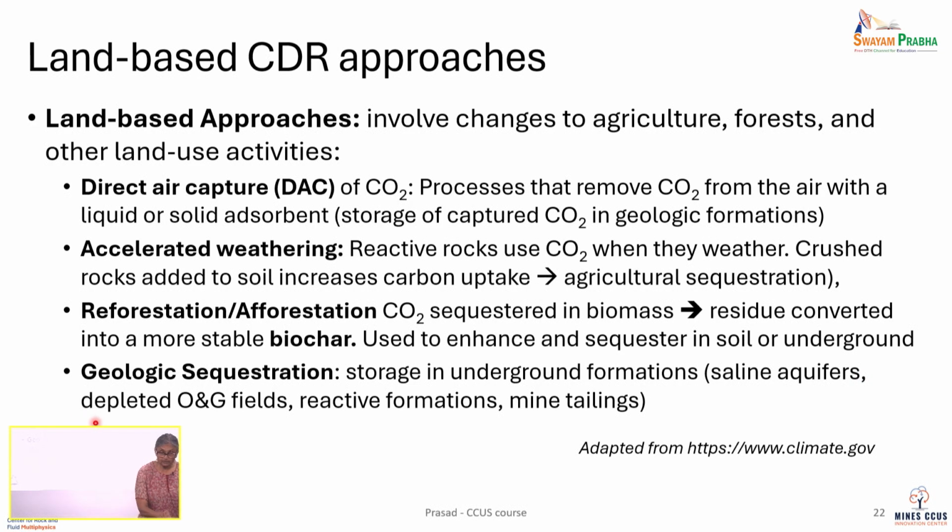We can go to depleted oil and gas fields. These are oil and gas fields that are not producing anymore. And so we can use them because we have depleted them to a point where they are under pressured from what they were when we started producing. So we have already a pressure buffer that we can use to store up and pump it back to the pressure where it was before oil and gas was produced.